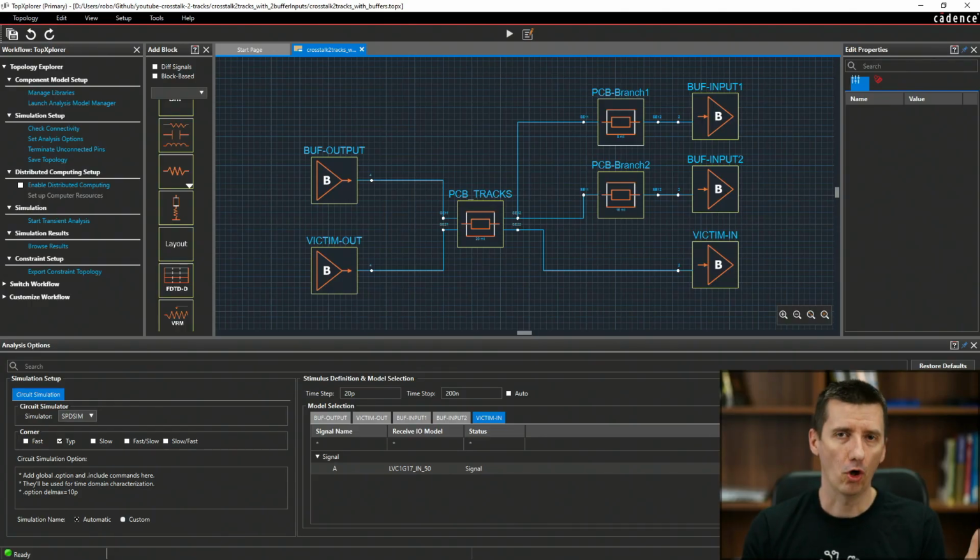There are all kinds of rules of thumb which can help you to decide how critical the length of your signal is. I read it's like 1/10 of the wavelength or 1/12 of the wavelength. I don't know exactly, but I can give you an idea how it looks in this simulation.